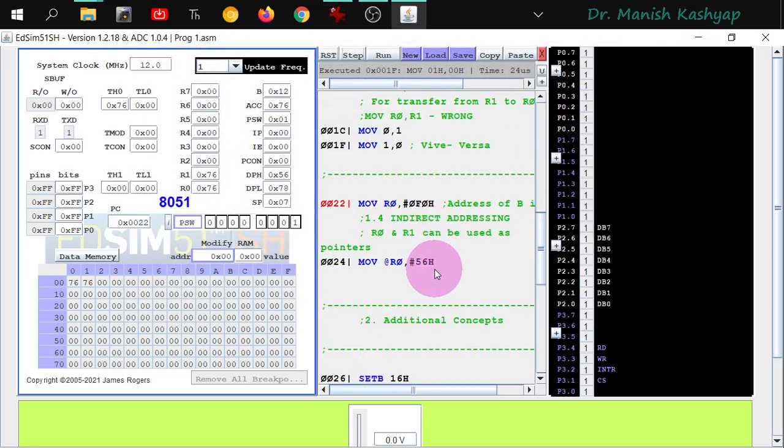After this, let us now move on to indirect addressing mode. What is indirect addressing mode? This is what we mean by pointers. So from here, the concept of pointers begins, right? Before studying this mode, let me initialize this R0 with F0H, right? So let me just execute this command. I'm initializing it on purpose to just make these things different, 76 and F0.